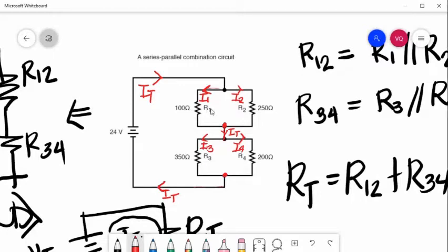So solving for I1 here, you can use the current divider theorem. Also, all of the branch currents, you can use the current divider theorem. Later on, we will solve the branch circuit currents and the voltage drops, but we will try to solve more total resistances in different kinds of series parallel combination.